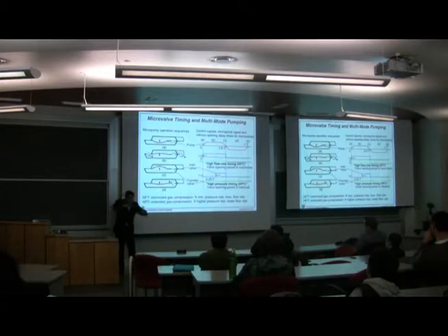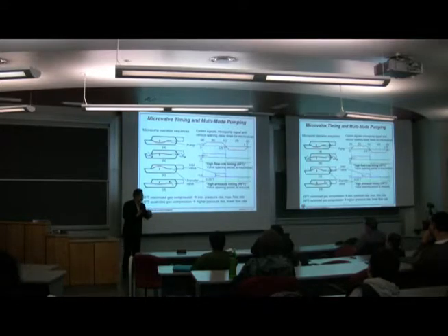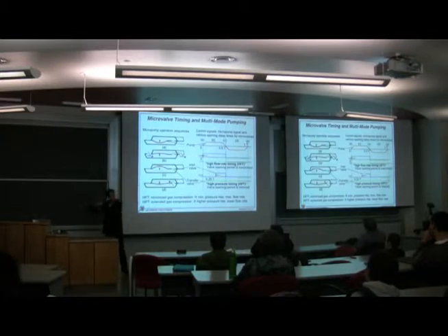If, as soon as this membrane starts compressing the air at the bottom, you immediately open the valve, then of course you give it minimum compression, which means less pressure generation, but the maximum flow transition, and therefore maximum flow rate.